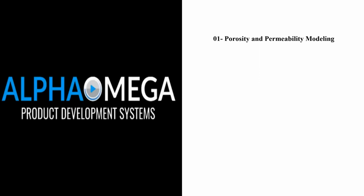Porosity and permeability modeling. ANSYS Fluent allows users to define the porosity and the permeability of the porous medium. Porosity is the fraction of the total volume that is not occupied by the solid matrix. Permeability, on the other hand, is a measure of the ability of a porous material to allow fluids to pass through it. ANSYS Fluent uses these two parameters to simulate the flow through the porous medium.